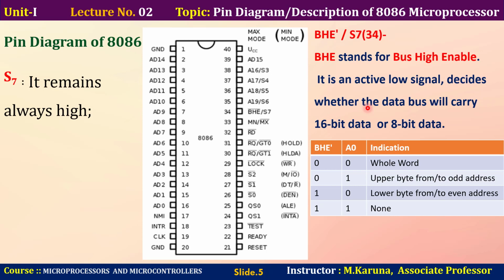These are the read cycle and write cycles. For example, let us see the time multiplexed lines, meaning address or data. During T1, this group of lines carries address bits. In other timing cycles, these lines carry data bits. Before starting any operation, initially the processor issues the ALE signal, which is an active high signal. Okay, these are the status signals S0 to S2, and the address status for upper or higher order bits A16 to A19 are carried by this bus during time T1. In other timing cycles, status lines S3 to S7 are transferred. Likewise, signals are carried out with the help of all these pins.